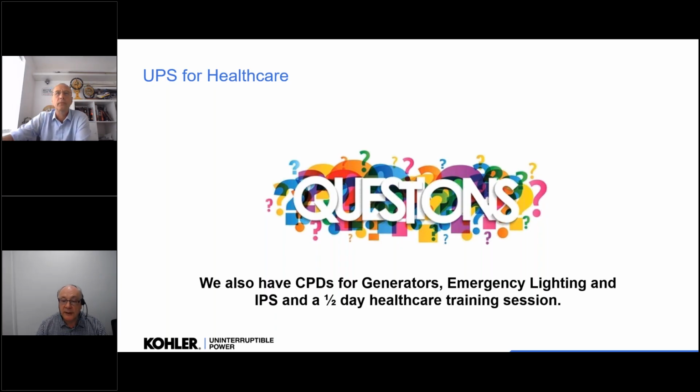Thank you. A lot of questions coming in. Another one is, what is the maximum recharging rate of a system after use, and do hospitals increase supply capacity to cover recharging? Okay. Again, very manufacturer specific, and also depending on the autonomy of the battery. So a UPS will have a charge capability, and with a VRLA battery, we will typically charge it at C10. So if it's a 100 amp hour battery, we charge it at 10 amps.